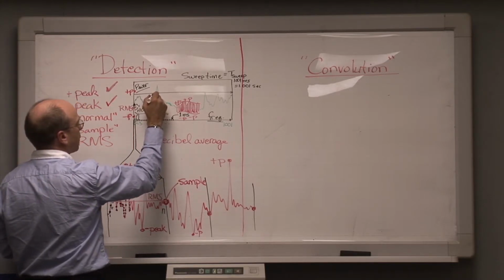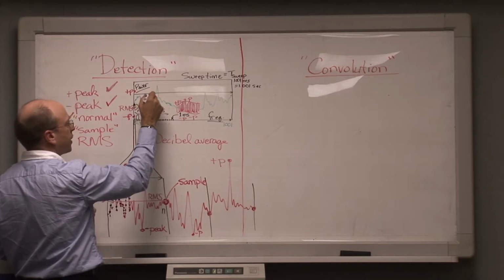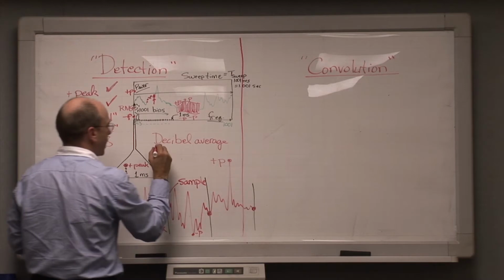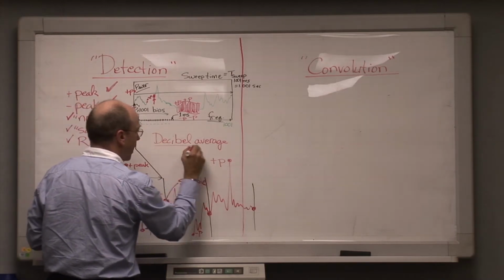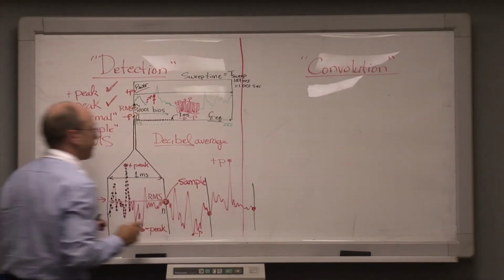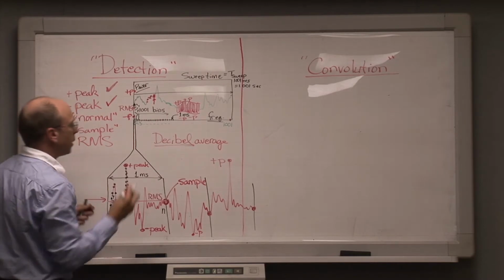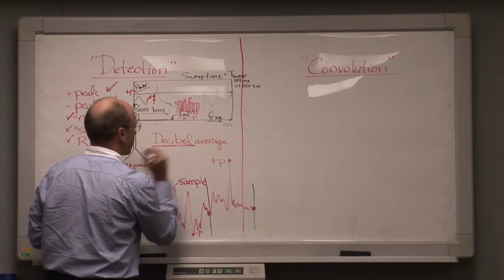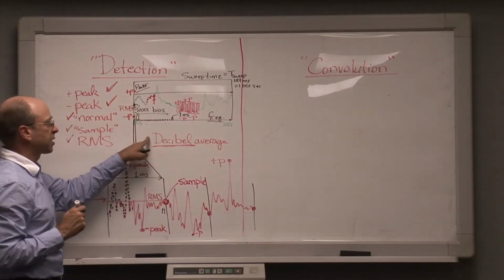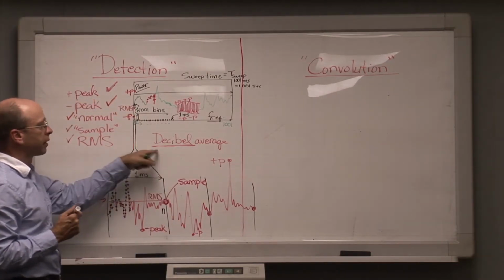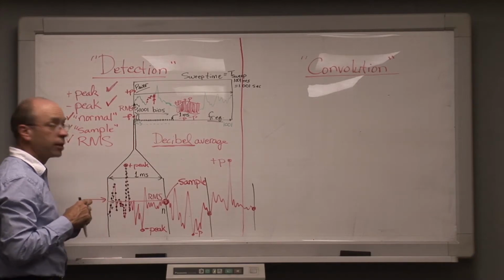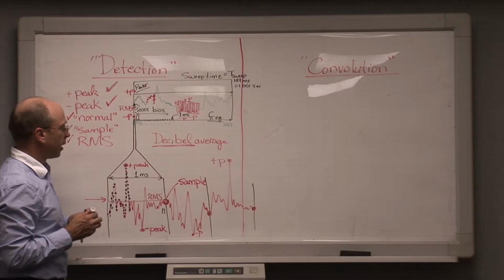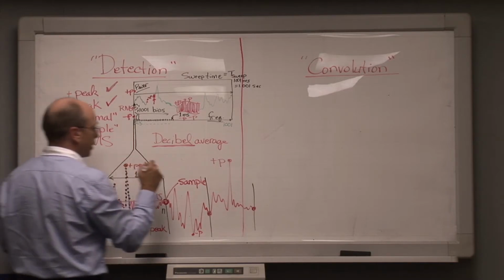On a third sweep, it might get a power value here. Then it adds all 3 together, divides by 3, and so forth. And this actually takes an average of decibels, not a linear power average, if the spectrum analyzer is being run in this mode. This is a screen trace display mode. Just be aware that if you use it, you are getting average decibels, not linear power average, and there is a difference. How much of a difference you get between the two depends upon the type of waveform that you're trying to measure.